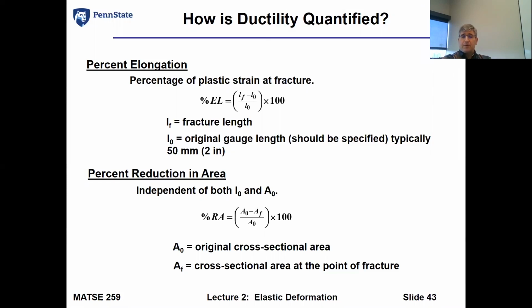In a lot of cases, what we're going to be looking at, especially as we start doing tensile testing, is a cylindrical type sample with a gauge length. And within that gauge length, we're able to measure that change in diameter. And that's all the percent reduction in area is. Imagine just a circle, and as it changes, we go back to what we thought of with Poisson's ratio.